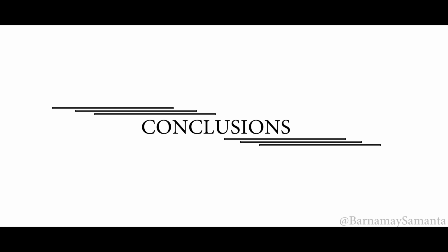Based on the numerical results, the correlative expression of stagnation Nusselt number between Nu0 and δ/D, Re, dj/D is obtained. Stagnation Nusselt number increases with the increases of protrusion relative depth and jet Reynolds number, and stagnation Nusselt number on protrusion target surface is larger than that of smooth target surface. Based on the numerical results, the correlative expression of average Nusselt number between Nu and δ/D, Re and dj/D is obtained.